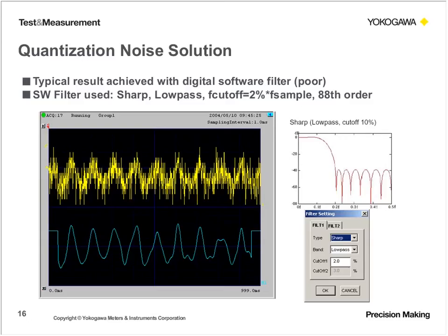And you can see that even applying the filter, we don't get a good recreation of the sine wave signal. The waveform on top is your typical noise applied to it, and that's because I used a low bit resolution instrument. But you can see that if you apply a filter, it doesn't give you a very good solution to this quantization noise.